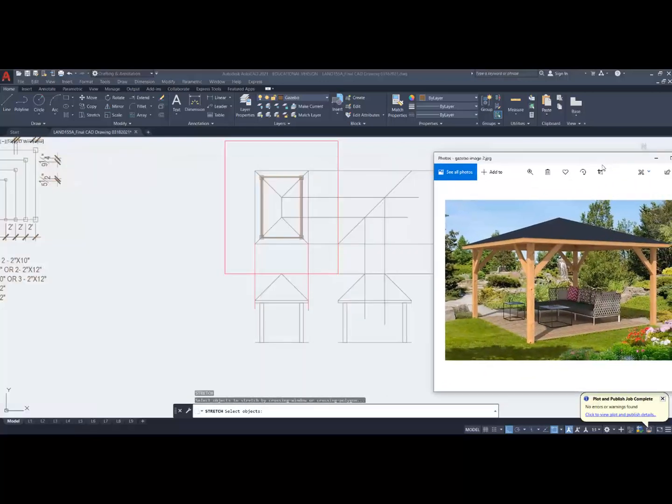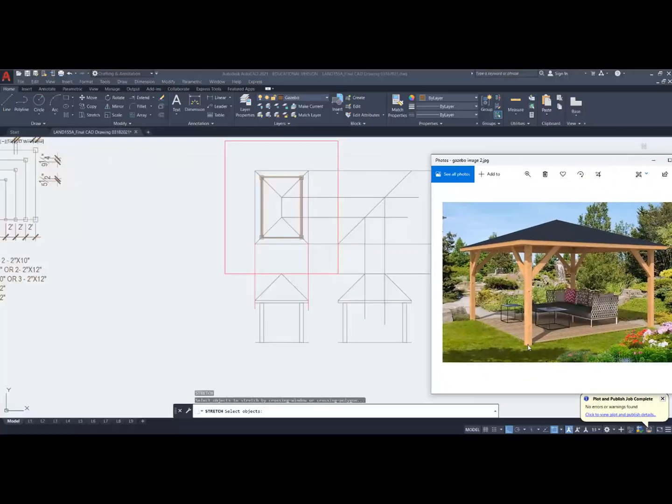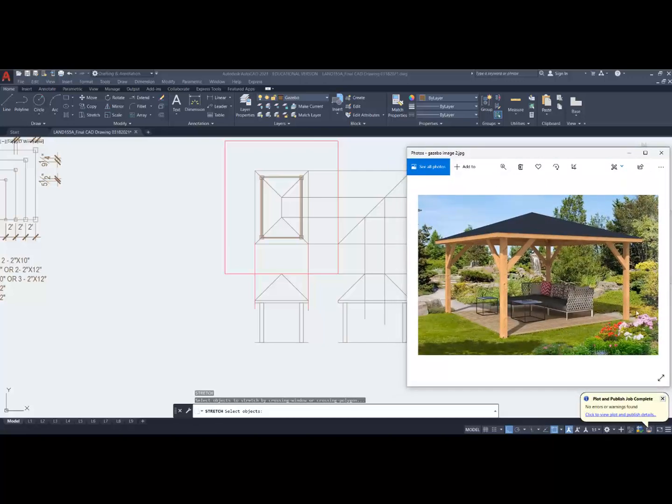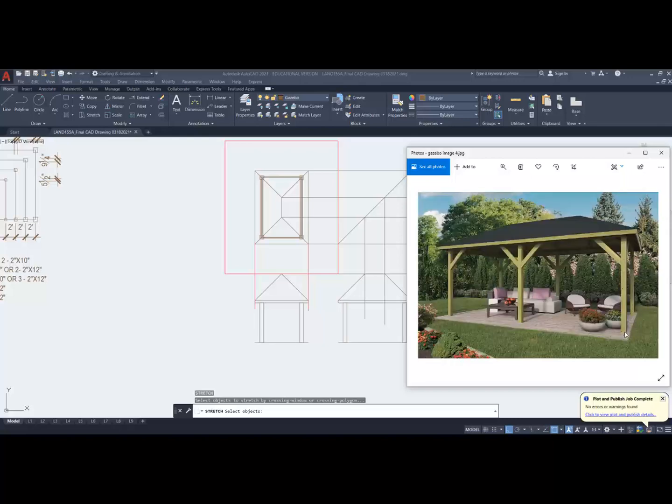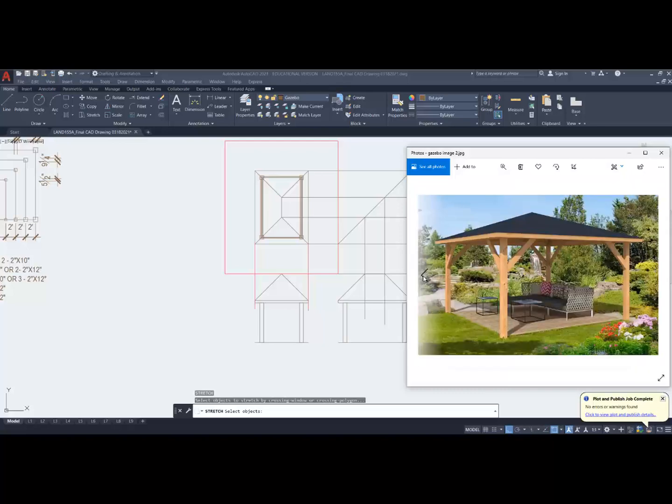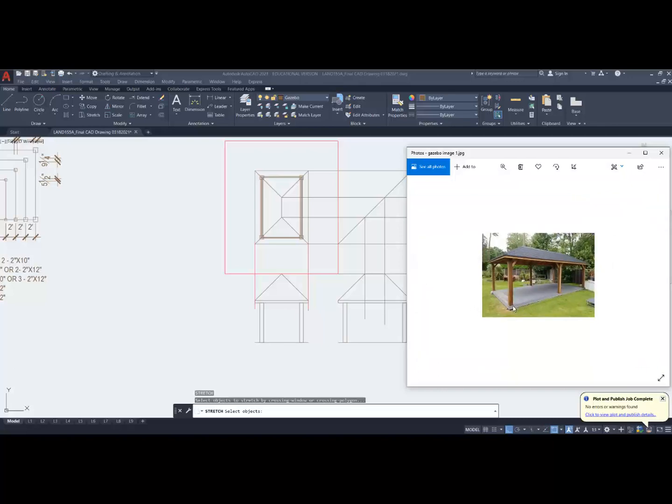So when you're looking at this diagram here, I've drawn the posts. Now these posts are going into the ground, which isn't really a good technique, only because they're going to rot after some time. You can see these posts are actually sitting on pavers, and they've covered the base because they've got some steel support underneath, which will go to a sonotube. And in order to cover the mechanical features down there that may not be exactly attractive, they've put basically a base. And that's a nicer effect than this. This may have been buried right through, which again is not an ideal situation. Putting some sort of base to cover how you've actually put it in makes a bit more sense.